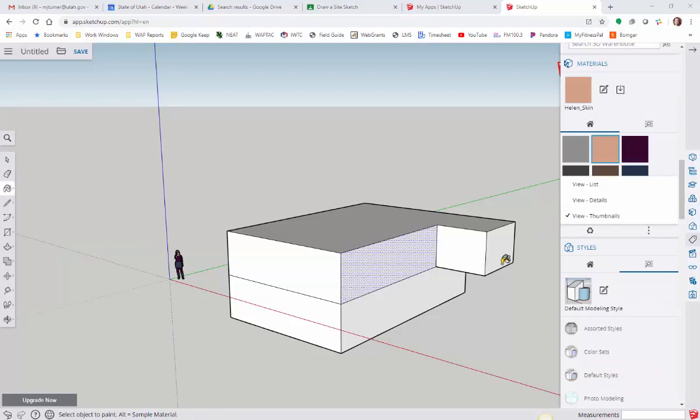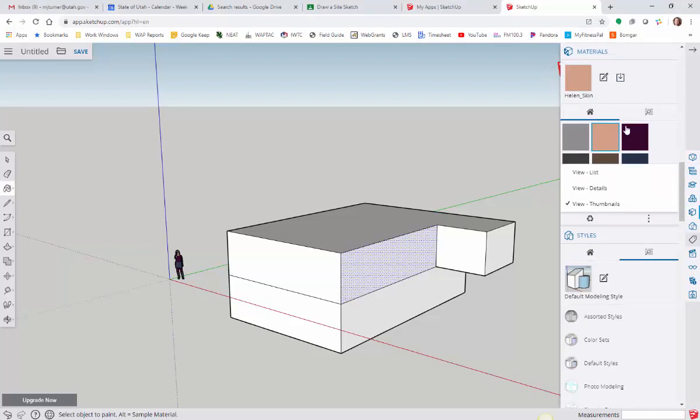There is one last thing that I use a lot when I'm drawing in the Weatherization program. Once I've drawn what represents my thermal boundary, I like to color each surface once I have entered it into the audit. To do that, you'd scroll down to materials, and you can select a color or two here in this freemium version. So I'm just going to select this color here, and then when I go back out onto my canvas, you'll notice I have a paint bucket, and basically I can start painting things.